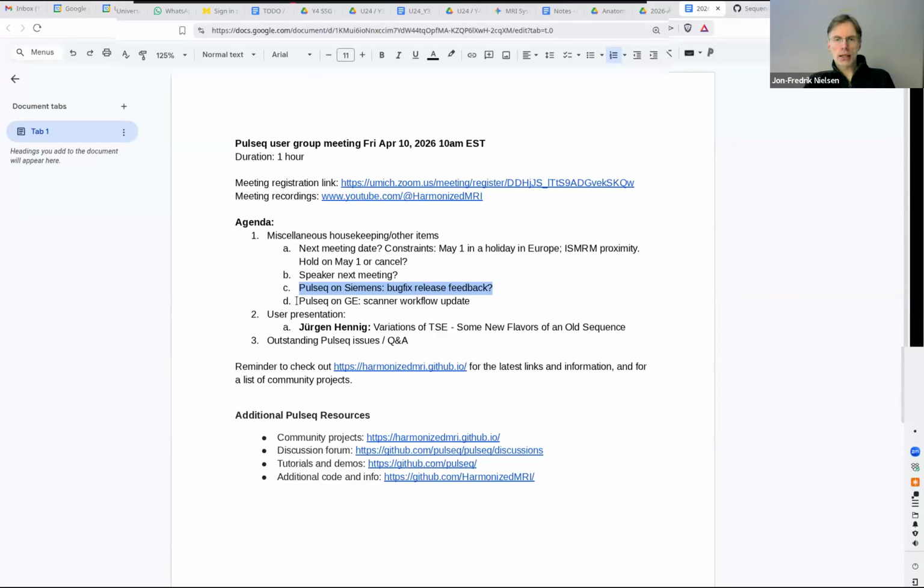what you just discussed aligns pretty well with what's going on in GE. Most scanners have a minimum dwell time of 2 microseconds, probably for the same underlying reasons that you just described, except on the head gradient system, where I believe they can do 1 microsecond. But it seems like we should probably limit our dwell times to 2 microseconds or greater. That sounds like a good practice.